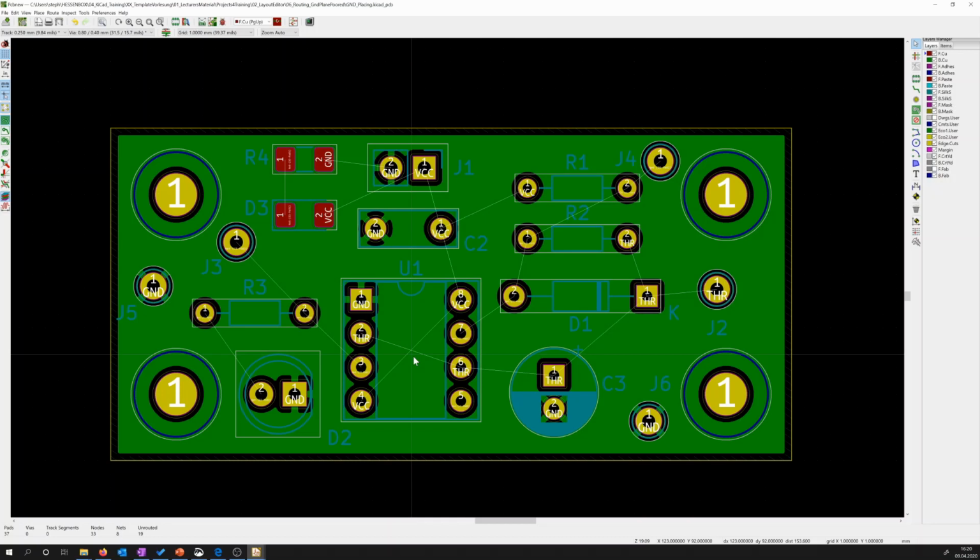If you check the data sheet, you will see that the supply pins are pin 1 and 8, and pin number 4 is the reset pin, which is held to VCC so as not to reset the IC during operation. That's fine and very good, because this means this pin doesn't consume any power. There's more or less a static connection.